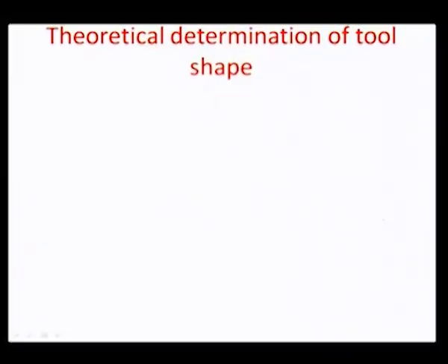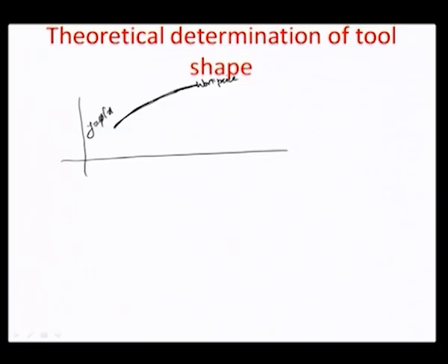So let us look at what we did in the 2D case, just reviewing what we said in the last few lectures. Supposing there is a certain tool surface, for example this is the tool surface, and also the workpiece surface, with a certain topology which is mapped by some function, let us say y equal to phi of x, and these are all the so-called workpiece coordinates.